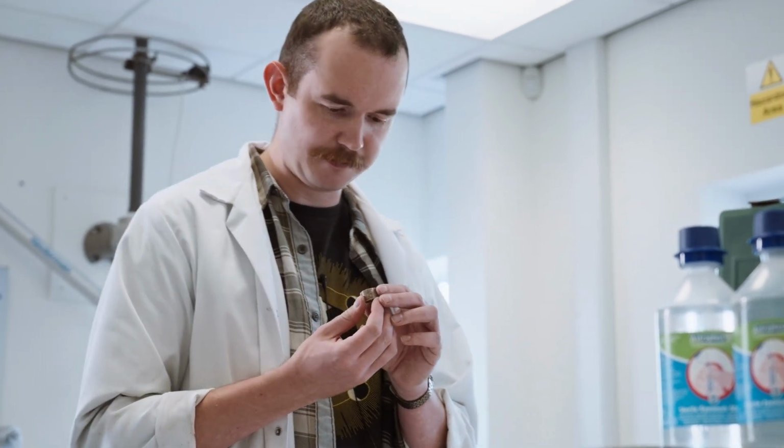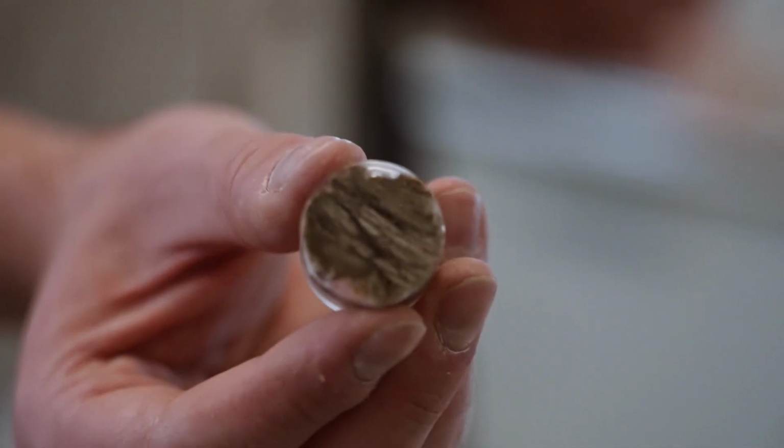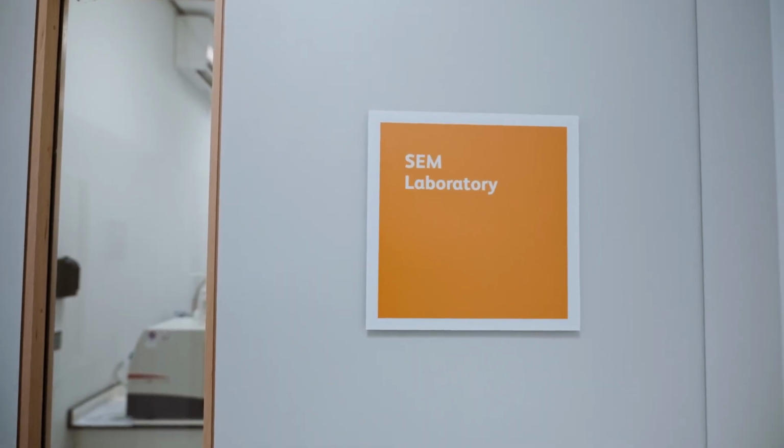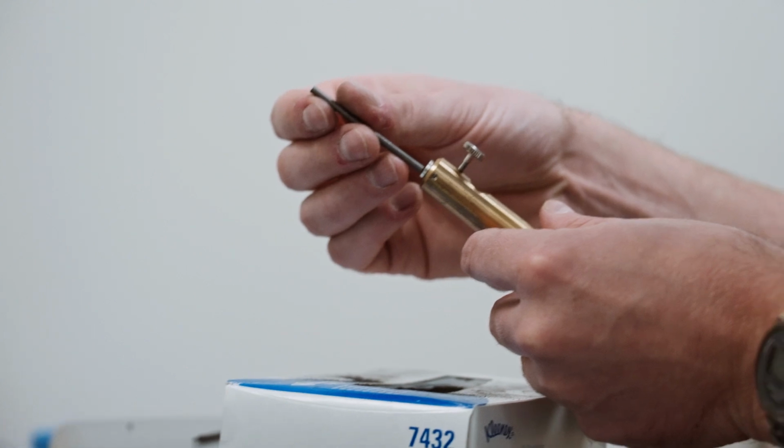Yeah, I'm happy with that. Before we put the specimen in the microscope, the surface needs to be electrically conductive, so we need to coat it in a really thin layer of carbon using the carbon coater.